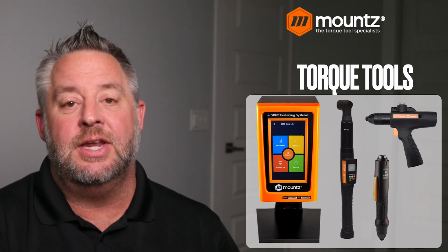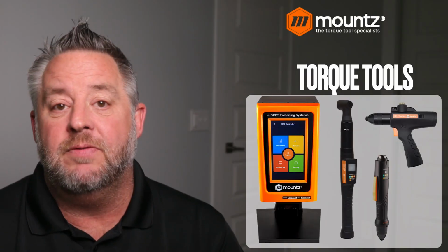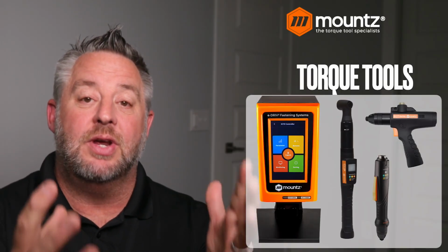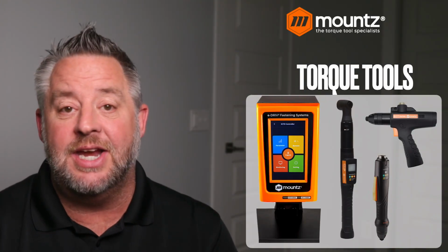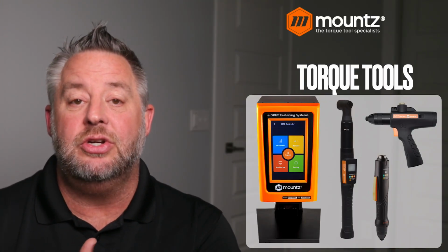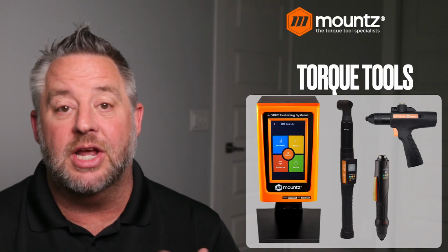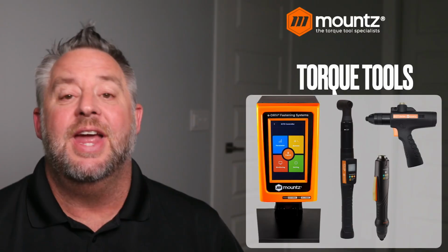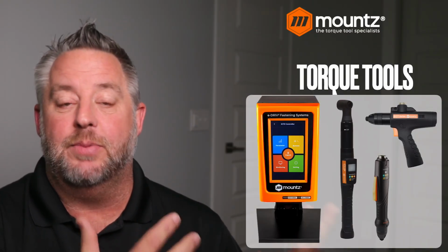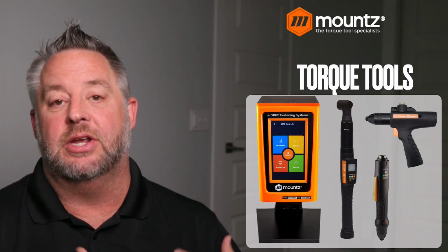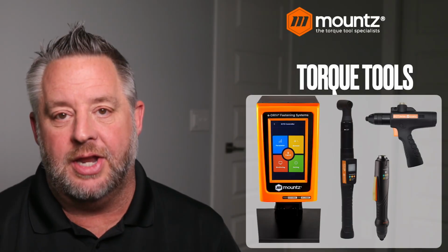And the current trend in the industry, which has been moving this way for a number of years now, is being able to capture all of that fastening data, store that data, and include it in an MES system or other type of data collection feature. And so you have the ability to look back at a particular job, a particular part, and you have evidence of what happened during that particular rundown.